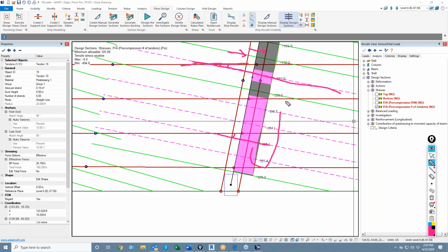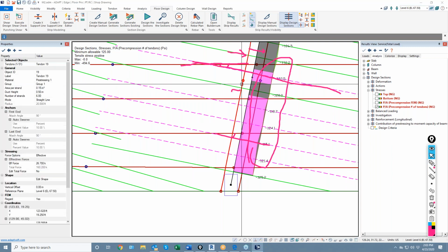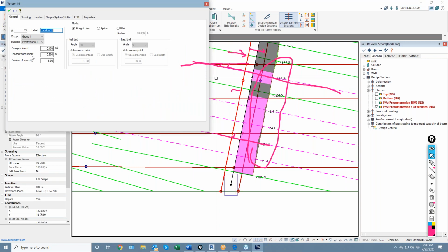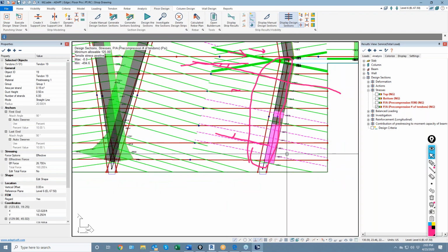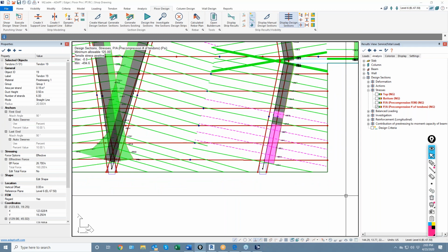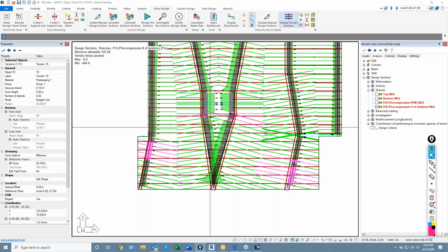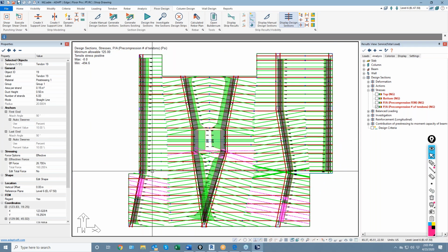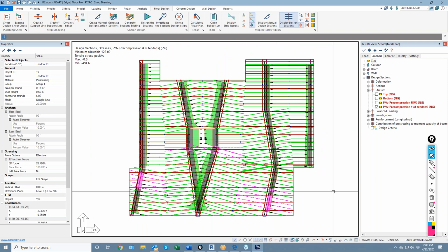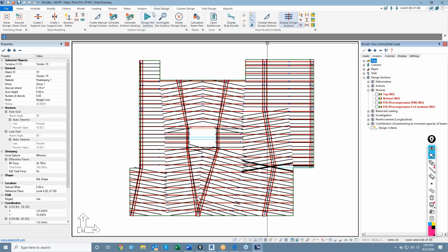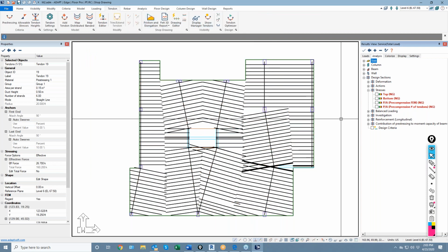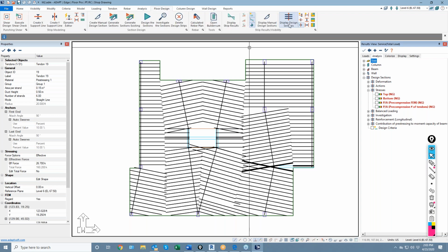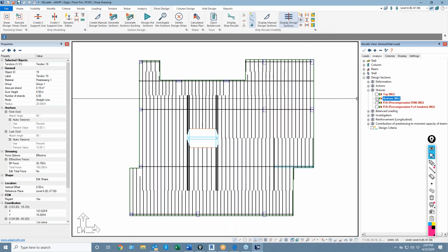But here you can see we're a little bit low on this line, so we might add another tendon here. I don't know how many tendons are there now. There's 6 times 2, so we might change this one to 7, have a total of 13, reanalyze, redesign to update that location. The same thing is going on here, and there's a little drop there. The second thing we might want to check after we solve the pre-compression would be the stresses. And if we go back and say, okay, let's go back to the X direction, I think it's a little easier to see that.